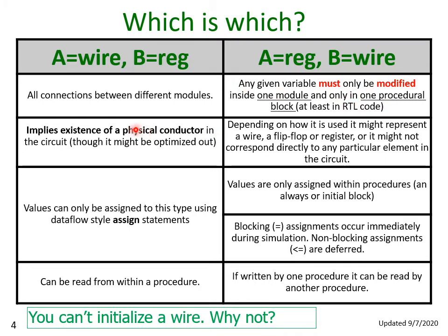That's going to be true of wires as well. So that's not just a limitation of use of variables. Now, how a variable translates into hardware is less obvious than it is in the case of a wire. I said the wire fairly directly implies a physical wire in the circuit, whereas a variable can translate into a lot of different things in the final circuit, and it's not unusual for that variable to not correspond directly to anything in the final circuit.